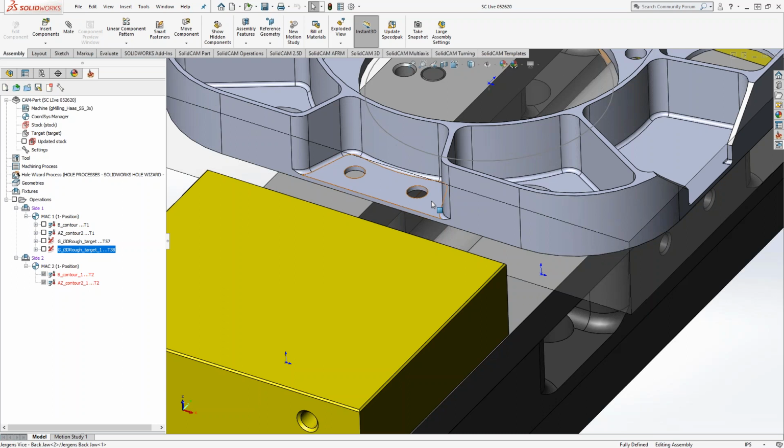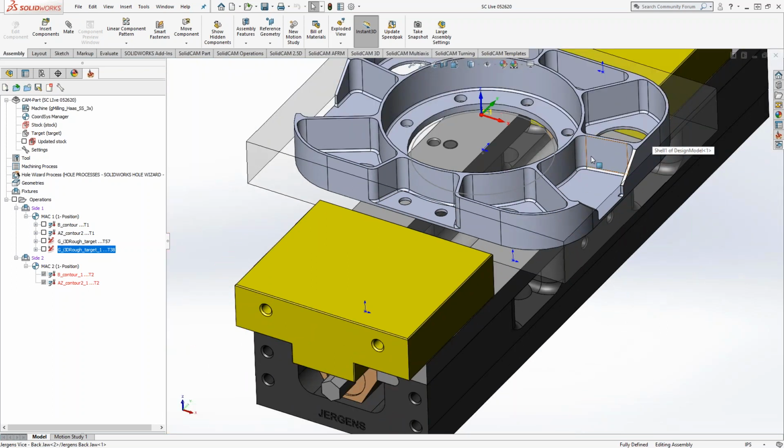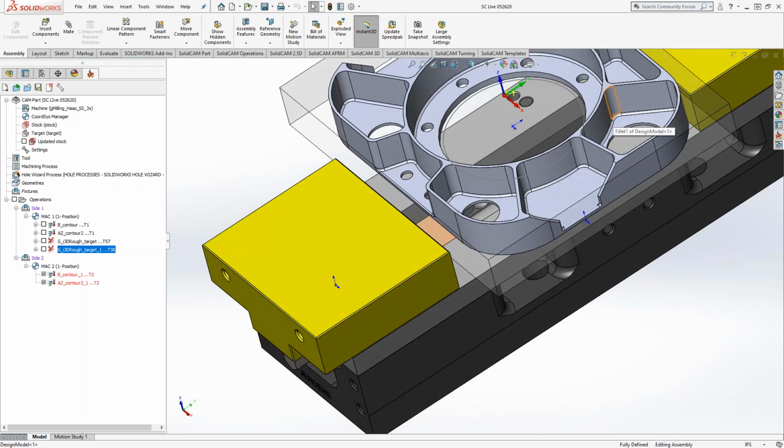So there's a lot of functionality with this toolpath, and this is why at least I suggest this being your first toolpath to use, because there's a lot of stuff in here that you might not be checking. You might not see how deep the pocket is, or the fact that the holder that you currently have selected probably can't reach there, but that's the tool that's in the machine, or that's the tool you're intending to use. You want it to just automatically figure out as best as possible how to use that tool. So 3D iMachining is a perfect toolpath to start with because it'll recognize all of that up front and figure a lot of that out for you.